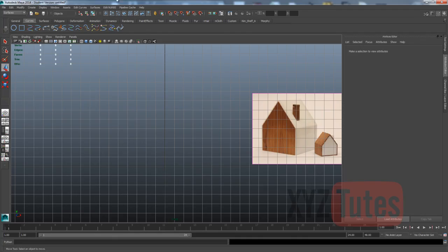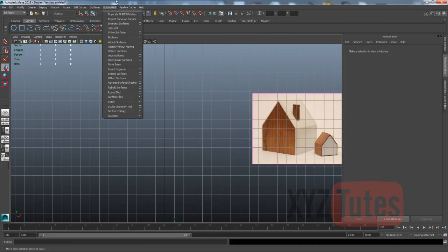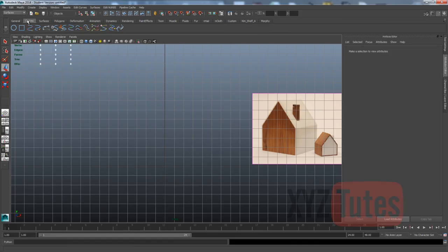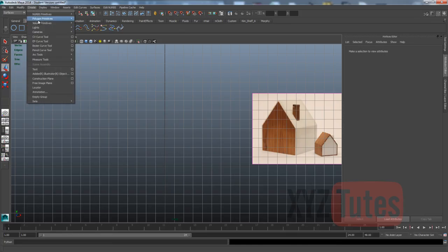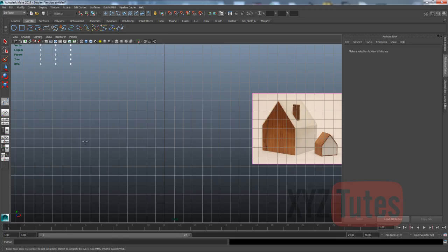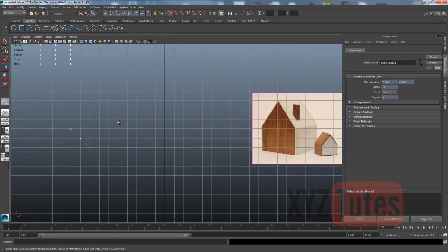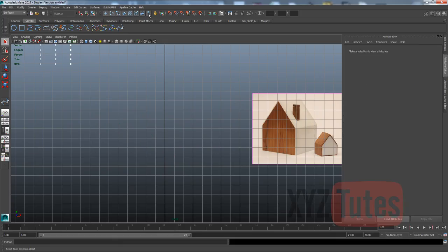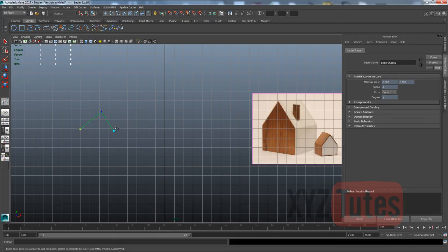And inside of here you can see I've got options for editing curves and surfaces and NURBS and things. Also got a curve tab here, and we're going to be working with a type of curve called a Bezier curve. These are the same type of curves that are used in programs like Photoshop and Illustrator for constructing things. They're really nice and easy to work with. If you click, you just create a sharp line.